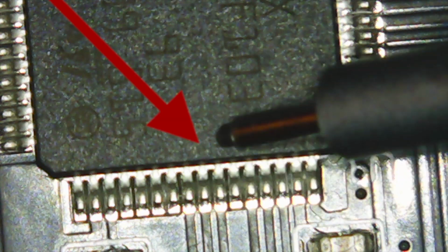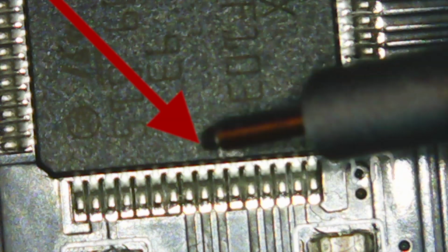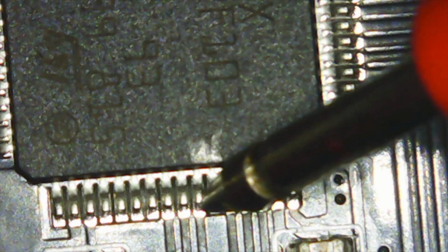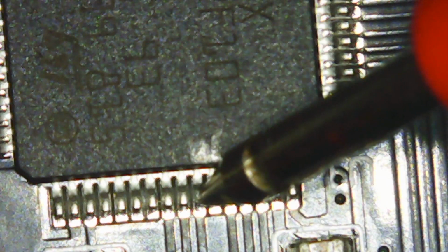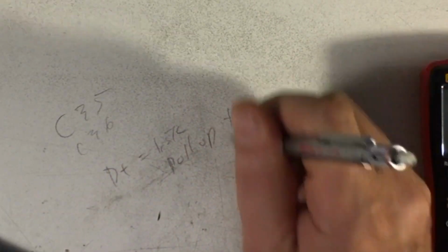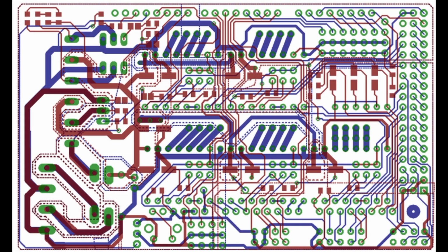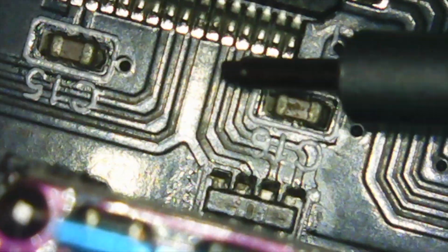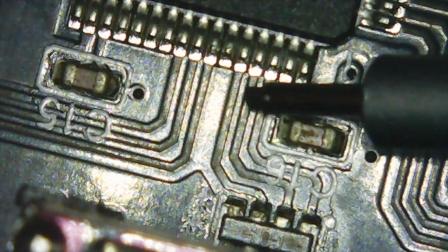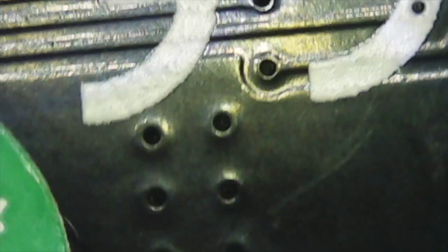First, we're going to count down to which pins are USART1 and then just mark them here so we know where we're looking. Do a little bit of very careful powered down and powered up probing and scribble some notes on our desk so at least we know what we're dealing with at the point of entry in the MCU. But again, no schematic and no connection diagram means that we have no freaking clue what's in between the MCU and the actual USB jack. And if these happen to be a four-sided board or have a ground plane or something like that, it's very difficult to trace that because we're not sure where the connections are.